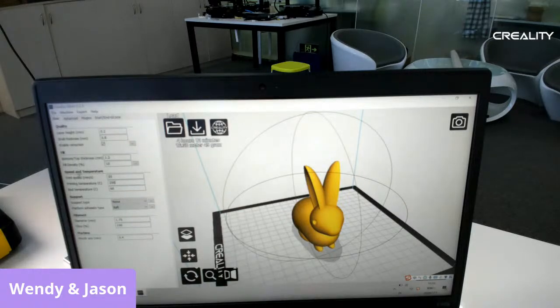Here, Michael said, hello, any suggestions for print speed, bed temp, nozzle temperature for transparent PLA? Transparent PLA? Yes. So I would say for the PLA, the nozzle temperature is going to be 190 to 210. And the hot bed, you can set it between 40 to 60. That would be nice. You probably can do a little bit of print test, even just print a really thin base to see how it goes, and you can do a little bit of adjustment from there.